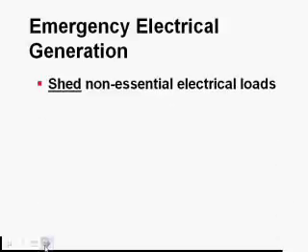Okay, you have an emergency. What are you going to do? Well, first thing is, I'm going to turn off stuff I don't need. Of course, you probably learned this flying a Cessna 172. If you have an electrical problem and you don't have enough power, you're going to try to conserve what you do have, so you turn stuff off you don't need.